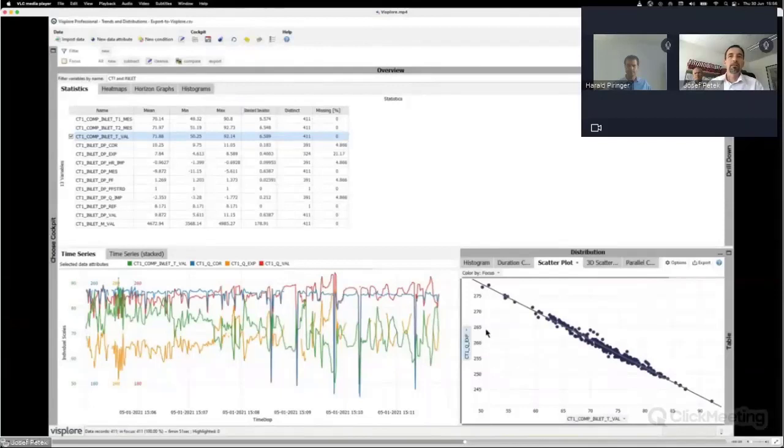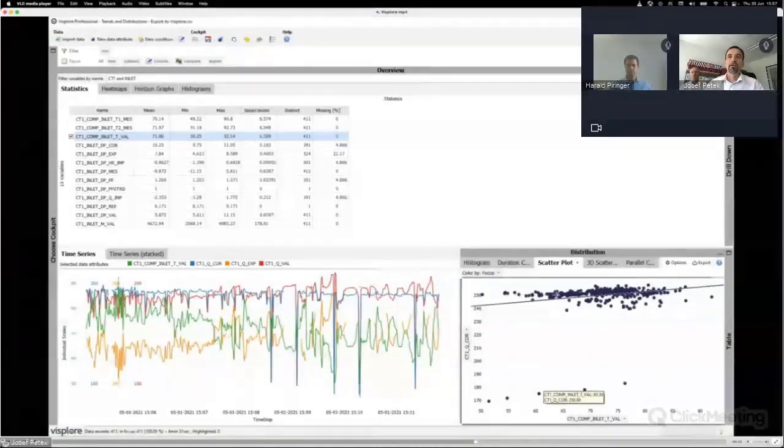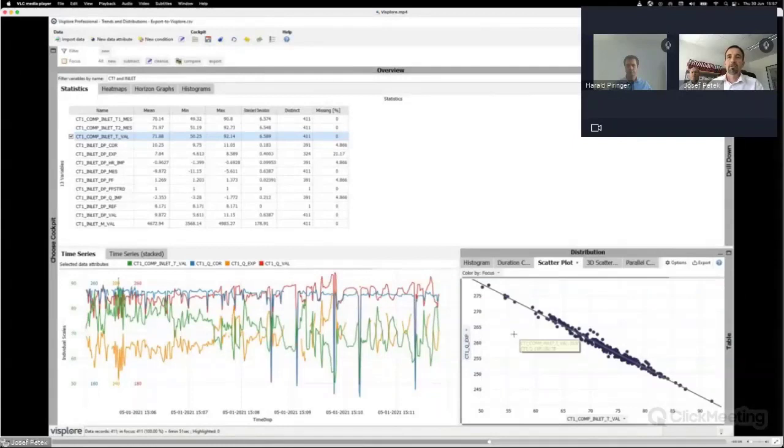We generate scatter plots where we put the KPIs over independent parameters. What we see here is the corrected power output. Corrected power output, as mentioned before, is expected to be independent of ambient temperature, which is the case for the majority of data points here, but there are some data points that fall off this constant expected number.